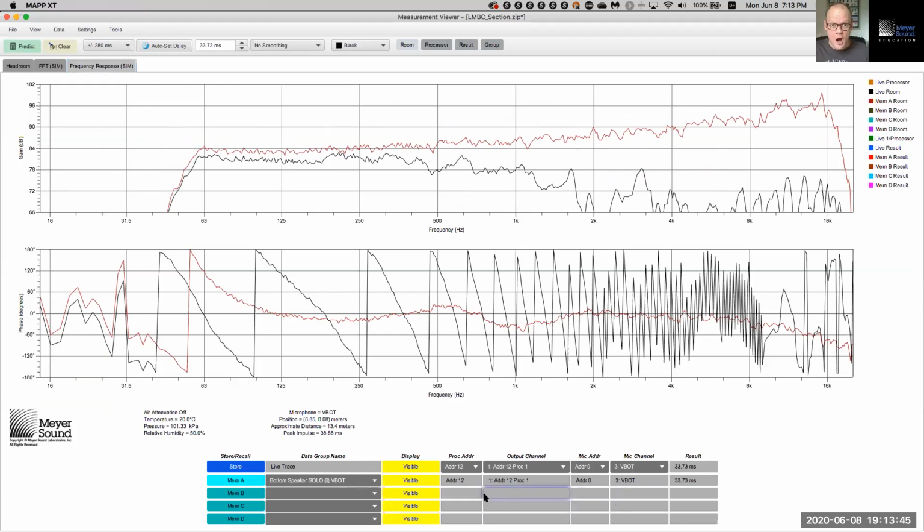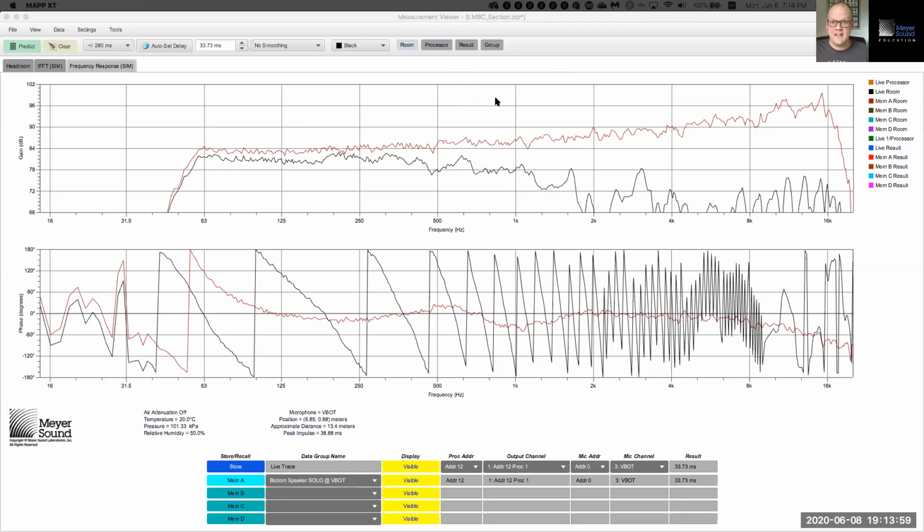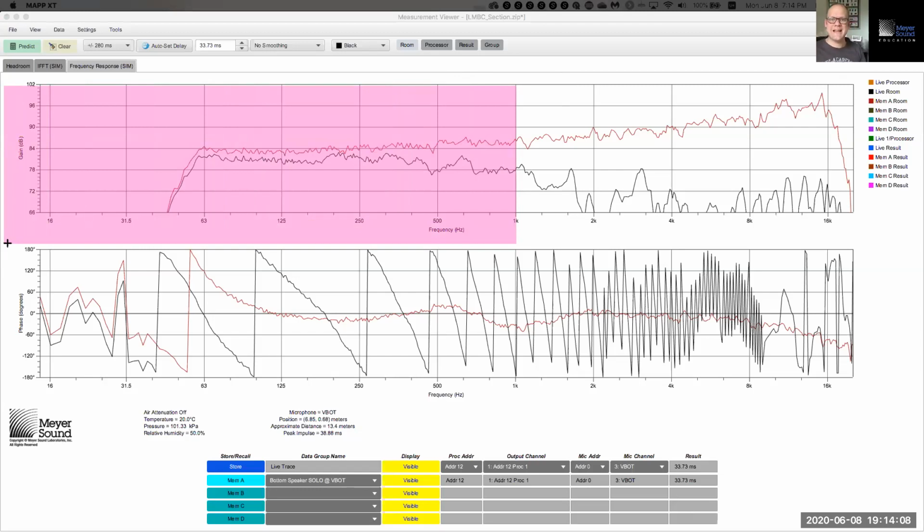So there's little or no isolation, as we call it. And if there's no isolation, then EQ becomes futile. We do not achieve isolation, for which it takes 10 decibels at least. There's no isolation between these two loudspeakers below 1 kilohertz. It's not until you go higher than 1 kilohertz that the top loudspeaker no longer exists in that first row, because there is 10 dB of isolation or more. Sure, above 1 kilohertz, that top loudspeaker no longer exists in the first row.